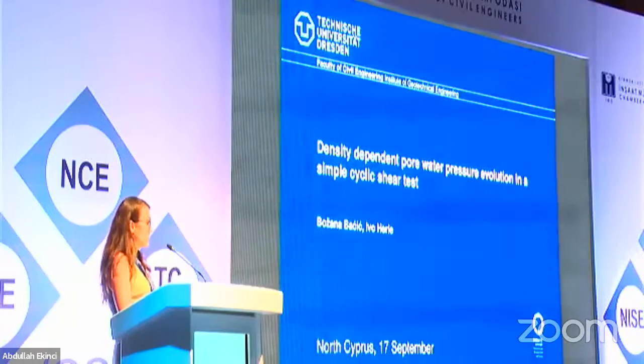saturated cohesionless soils. When subjecting these soils to external loading, pore water pressure is evolving and causing a decrease in effective stresses and therefore also stiffness and shear resistance. Now, if we consider the same sample preparation method, and if we test different soils under the same conditions, then we can safely say that different sands will respond differently to the same loading.